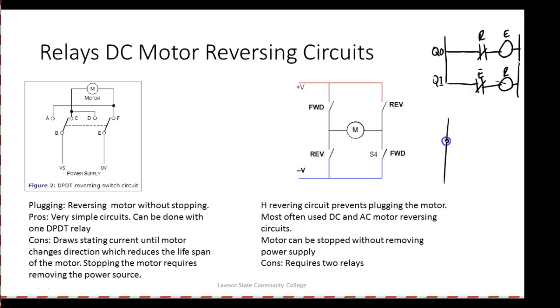Now, a motor starter is a relay that has an overload. The overload is actually over here on this side, and this would be one of the outputs on my PLC. This is the way we would wire them. Of course, our PLC is using sourcing outputs, so this guy right here is going to give me the plus. So what would we connect over here? We would connect minus, right? All our PLCs in here use sinking inputs and sourcing outputs.